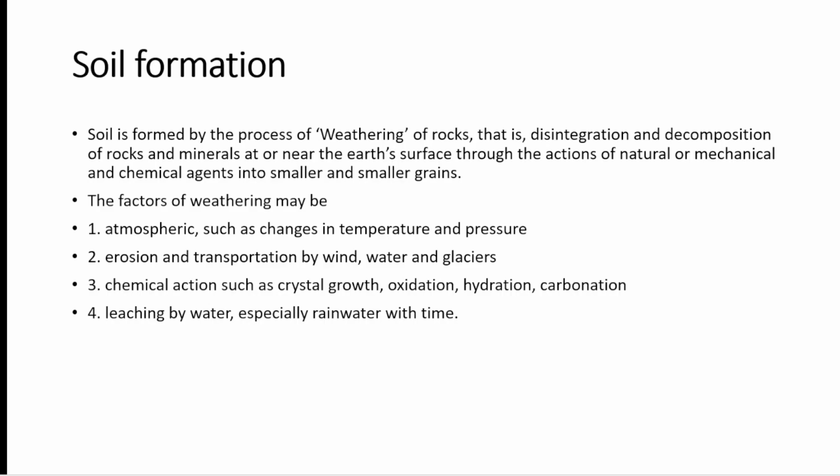Rocks are altered more by the process of chemical weathering than by mechanical weathering. In chemical weathering some minerals disappear partially or fully, and new compounds are formed. The intensity of weathering depends upon the presence of water and temperature and the dissolved materials in water. Carbonic acid and oxygen are the most effective dissolved materials found in water which cause the weathering of rocks. Chemical weathering has the maximum intensity in humid and tropical climates.